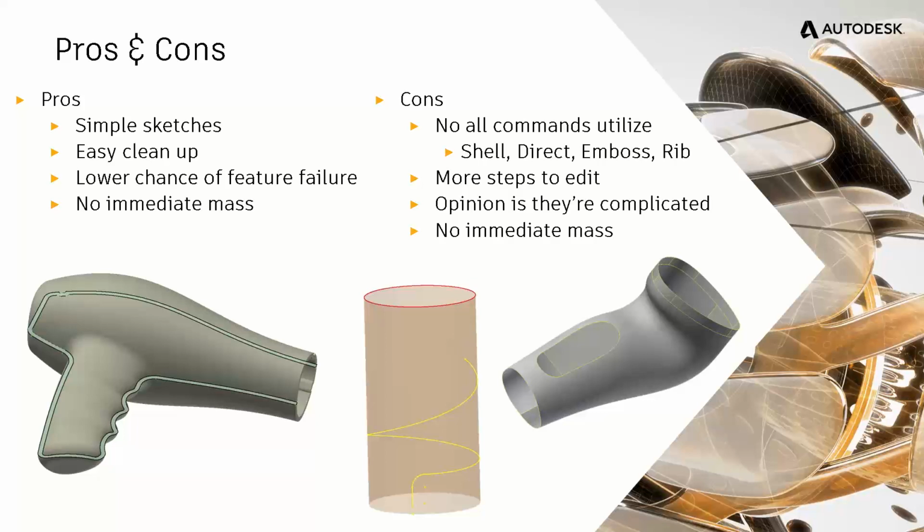The surface command had less issue with that than the solid form of it did. A few years ago, they changed the sweep command and enhanced it to where it doesn't have that issue as much as it did, no matter what way you go, surface or solid. So that got a little bit less evident, but you still have situations like that where the surface command is going to create it and just go about its day.